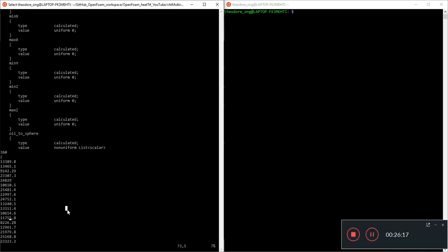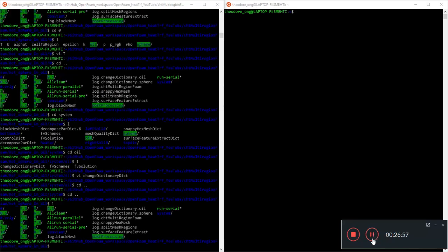So that's not very telling of where the directionality is. So we have to rely on the temperature to tell us where the heat is flowing. If it's flowing from the fluid to the wall, then it will be a positive heat transfer coefficient. Of course, we can actually test this by changing maybe the fluid temperature to 500, the sphere temperature to 300, to see how these actually change. So yeah, I can just do a very quick run of that.